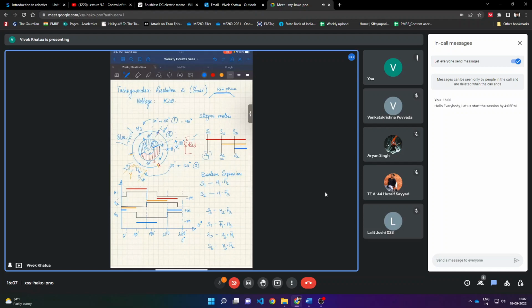That is how this is going to rotate. I'll be actuating my red phase to a peak when the line that bisects the north pole exposed to the coils aligns to H1, right? That is till when I'll be actuating my red coil.